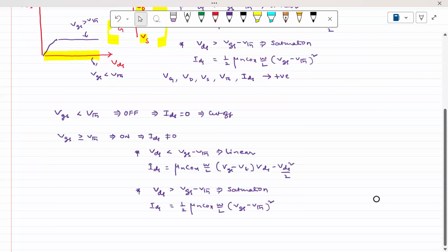Okay. So here, the PMOS is actually complement to the NMOS transistor. On what basis can you say it's a complement? For example, if you take the source and drain, instead of the N plus, we take the P plus. Instead of the N channel, we take the P channel. Instead of applying positive potentials, we apply negative potentials. Instead of P as the body for the NMOS, N is the body for the PMOS. That's the reason why they almost complement each other.